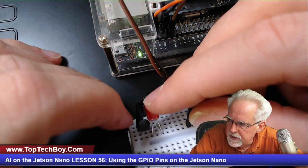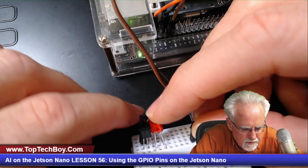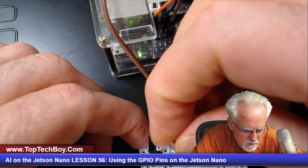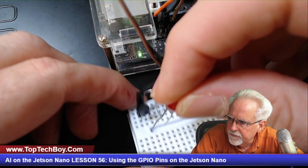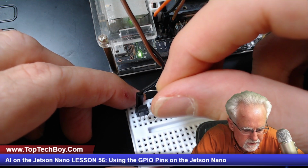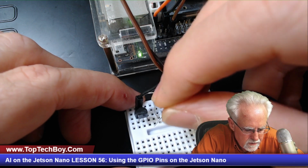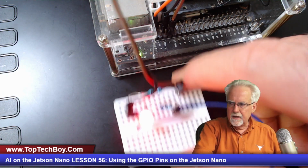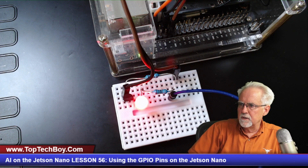And then let me just make sure I have my LED in the right direction. The LED is in backwards. It's the short leg that should go to, there it is. All right, so I hope you guys caught that. I confused long leg and short leg.